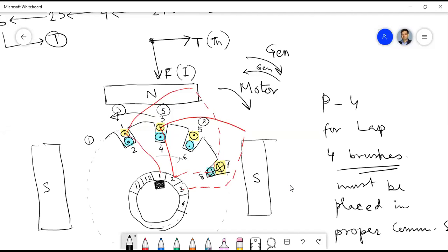The torque will change. Some anti-torque will be there. Magnetic torque will be opposite. So that will create a problem of rotation. If the torque alternates, how will the motor rotate? So to maintain unidirectional torque, the current which will flow in the next instant through the 7th coil side should change. Do you agree with this? It should change from cross to dot.